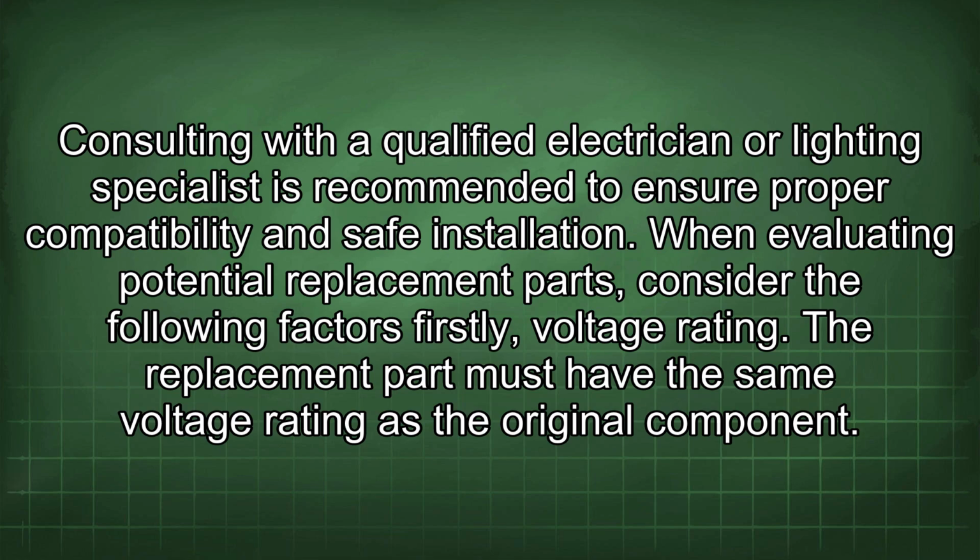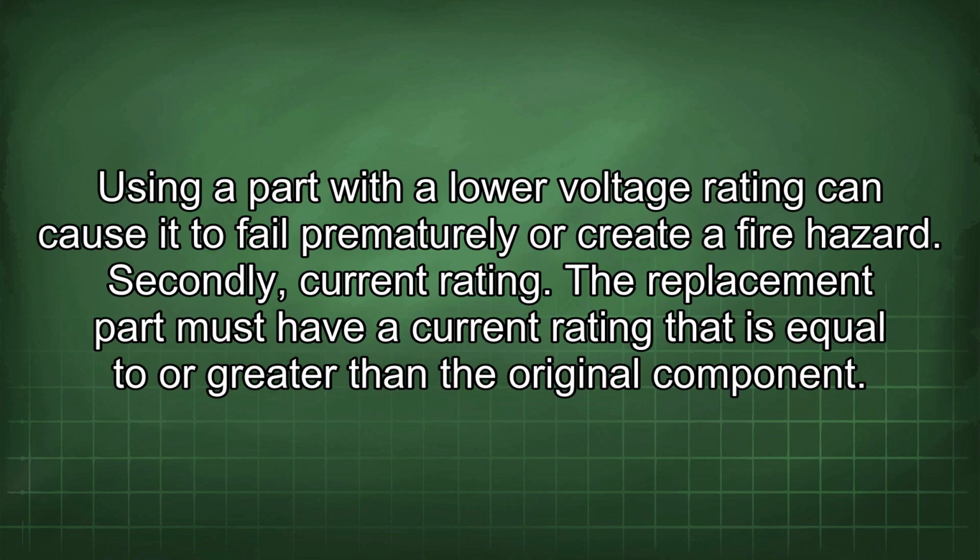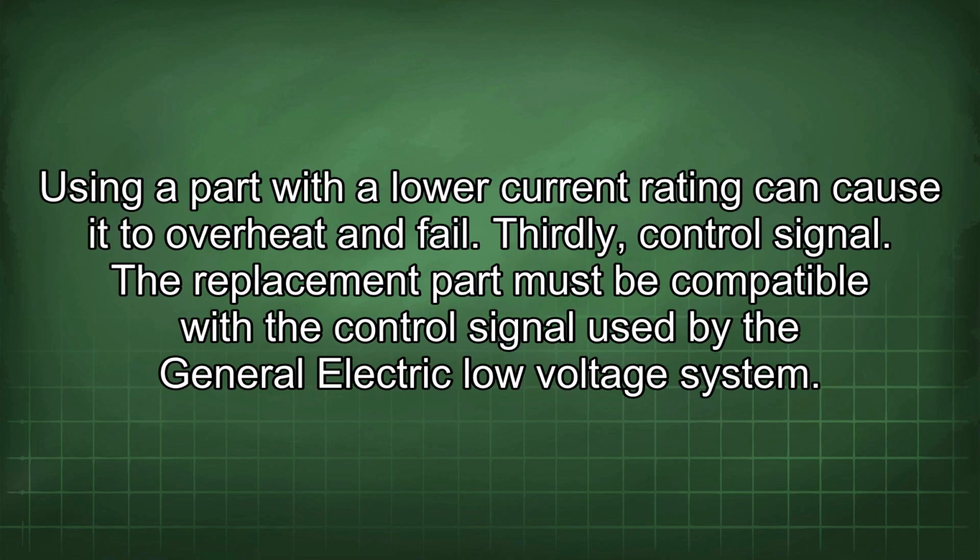When evaluating potential replacement parts, consider the following factors. Firstly, voltage rating. The replacement part must have the same voltage rating as the original component. Using a part with a low voltage rating can cause it to fail prematurely or create a fire hazard. Secondly, current rating. The replacement part must have a current rating that is equal to or greater than the original component. Using a part with a low current rating can cause it to overheat and fail.